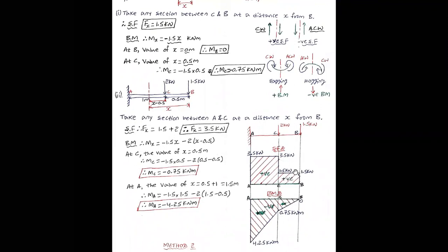In the previous video I have shown you how to draw the shear force and bending moment variation. In the description I will add those links. You can see how to draw the variation; in that lecture I have shown you. You need to remember a table. If a point load is acting, then the variation will be constant. So 1.5 kilonewton is constant.